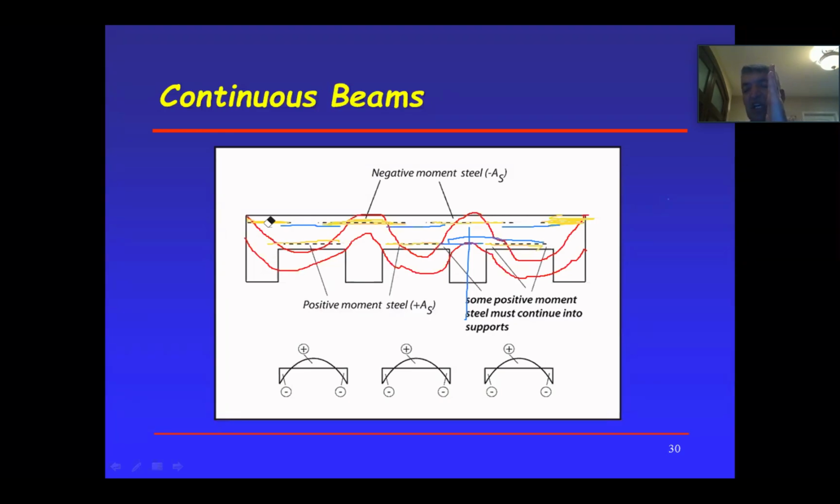Versus if you take a steel column and attach a steel beam to it with bolts, that's not fixed. So if that's the case, then we will develop a negative moment here, because this is continuous. It's not simply supported. It's fixed, per se. So that's why it does that, and I will explain it when I draw the shear moment diagram.